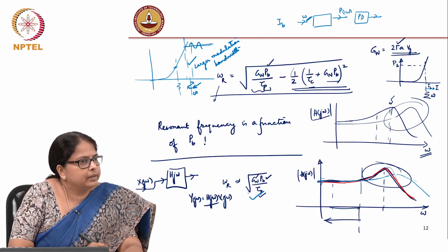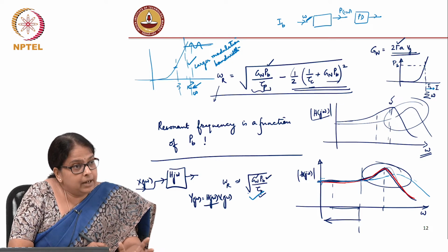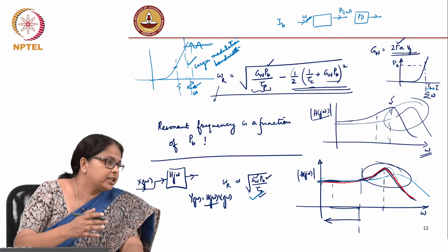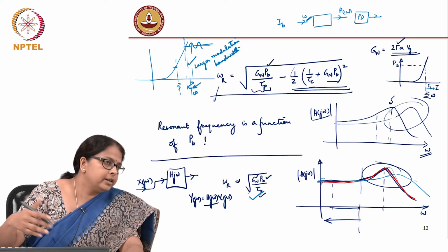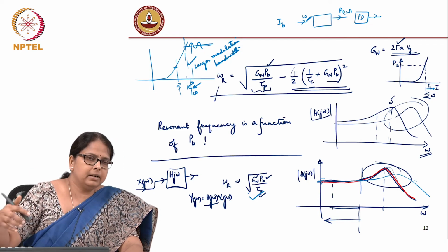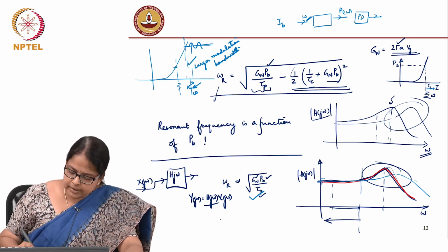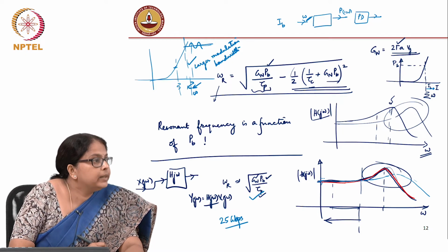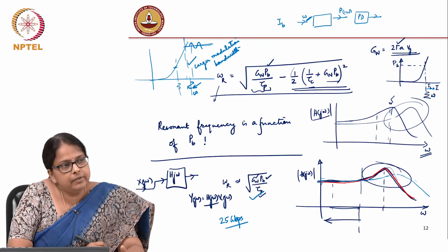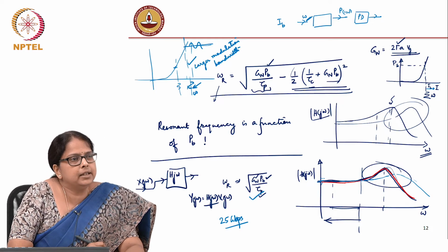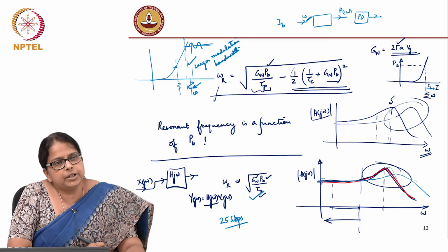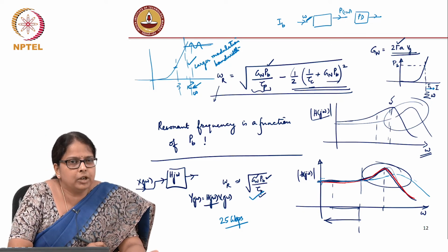Okay. And the state of the art today is that people have done direct modulation lasers. So, these are direct modulation lasers, meaning you are directly modulating the current of the laser to get the power on and off. 25 gigabits per second is common. You can get transponders which work at 25 gigabits per second. So, the bandwidth corresponding to that would be something like 18 gigahertz or 20 gigahertz. There could be one-off demonstrations. It's always useful to have this direct modulation on-off.